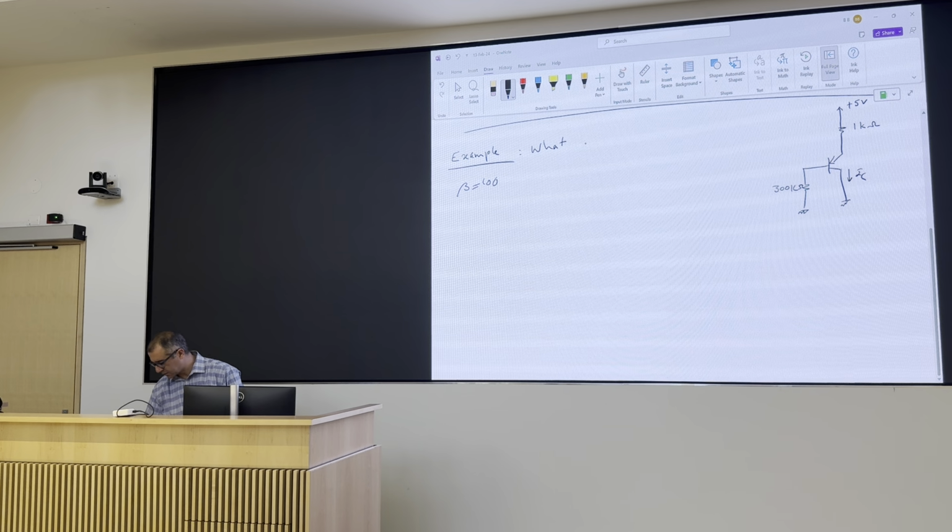And Early is a name, so E is always capital. This early voltage for your typical off-the-shelf transistors is 100 volts, 200 volts. It's a big, big number. So with a couple of volts of change in VCE, you will not see that change in current. For small integrated devices, it could be 5 volts, so you have a bit of a problem. You see that change in current with voltage more significantly in small devices, but in large devices you normally don't care. And because that's the focus of what you guys are learning, I'm going to leave it there.